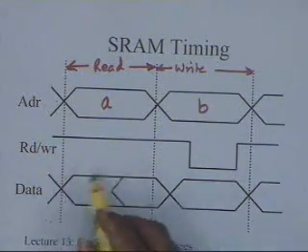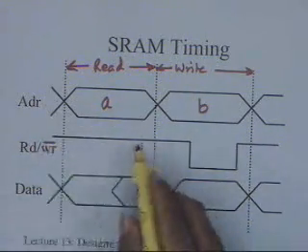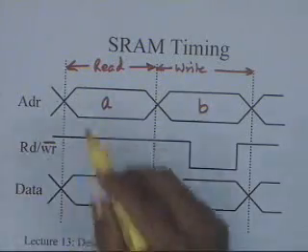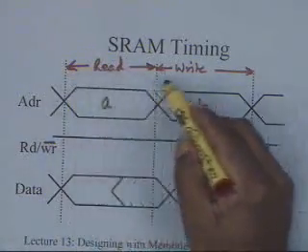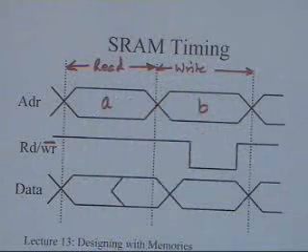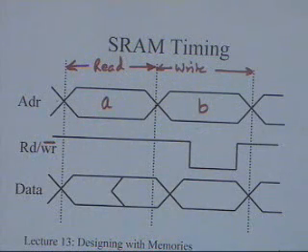Now this is the read part, this is the read cycle, and there will always be a specification available for what is the minimum read cycle time. Let us say the minimum read cycle time is specified to be 100 nanoseconds. It means you can do 10 million operations in a second on that ROM and on that RAM. You can write 10 million times. The number of reads plus writes that are possible in 1 second will be 10 million if your cycle time is 100 nanoseconds.